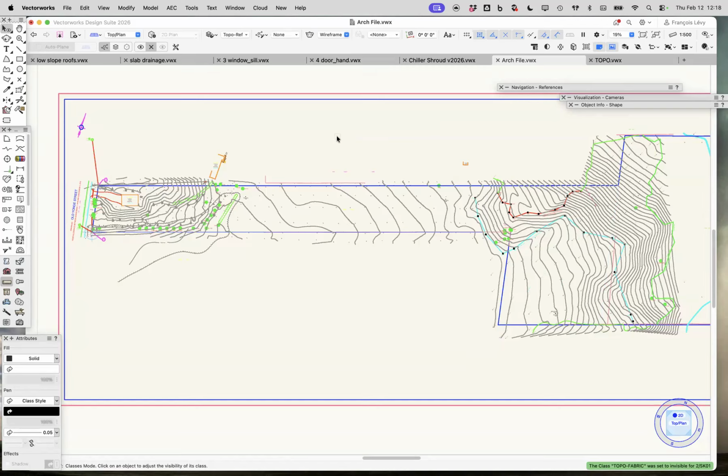Sometimes they do, sometimes they don't. Purging is a good first thing to do, purging a file. Classes, layers, symbols, the whole shebang. Why have this big thing? Plus, they sent it to you, so if you accidentally delete something important, you can always get it again.